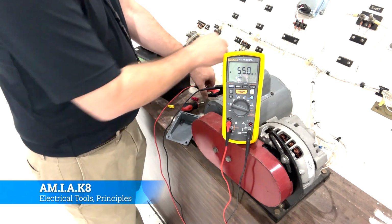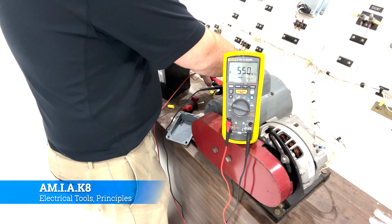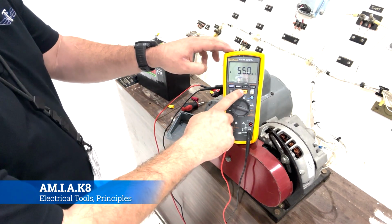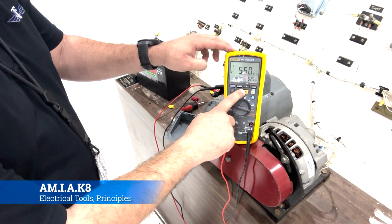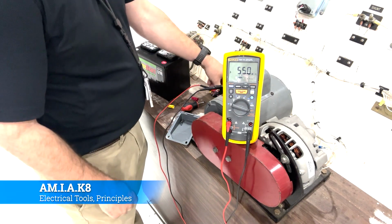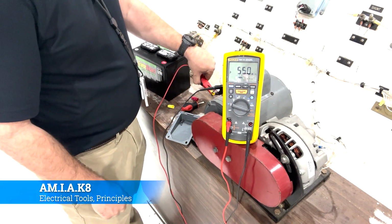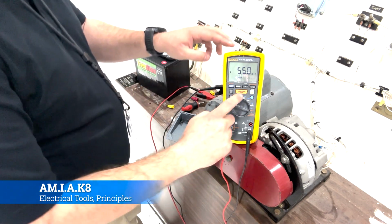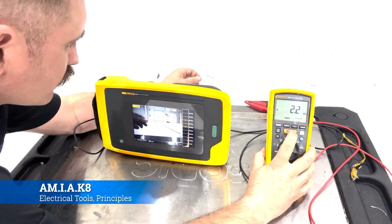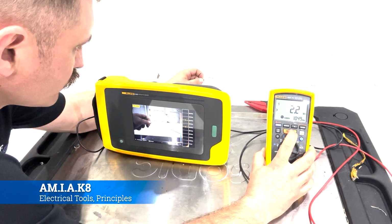That phase is good. So now we're just simply going to keep the ground in the same place. We're going to move it over to the next phase, and we're going to just repeat the process, and we should have something very similar. And there we go, greater than 550 mega ohms. So on a three-phase motor, we should have one more phase to check. So we're going to move it over there, clamp it on, hit the installation test, and we should get 550. So that's a classic way to use a megger.